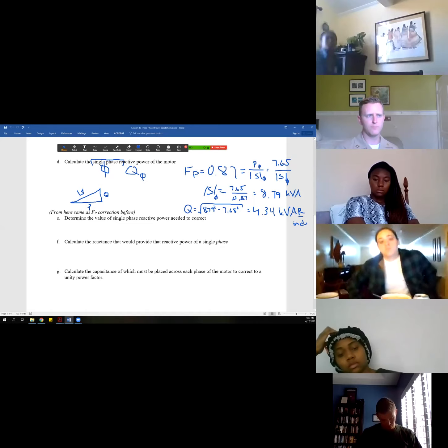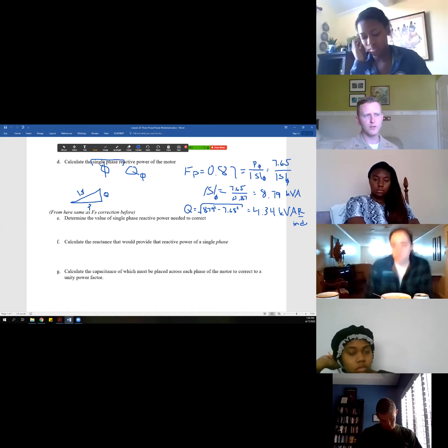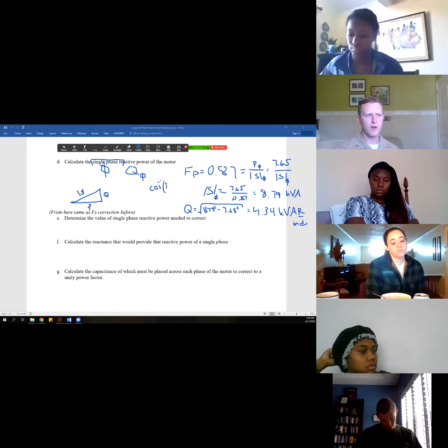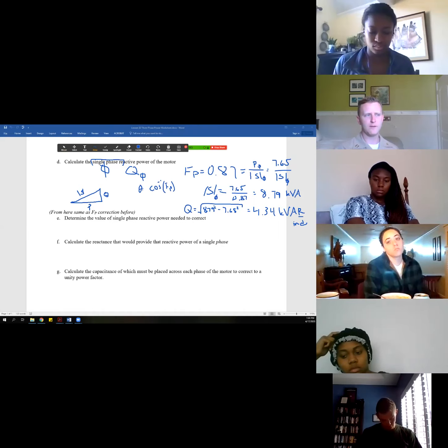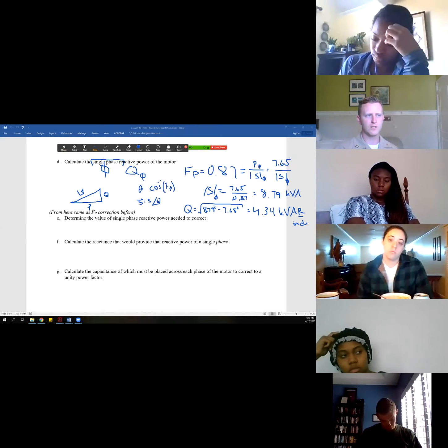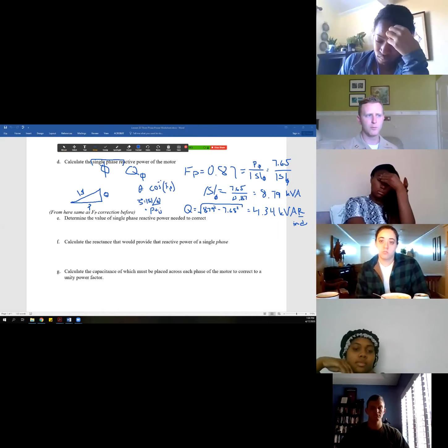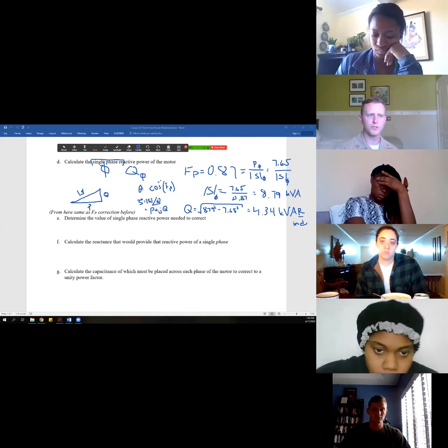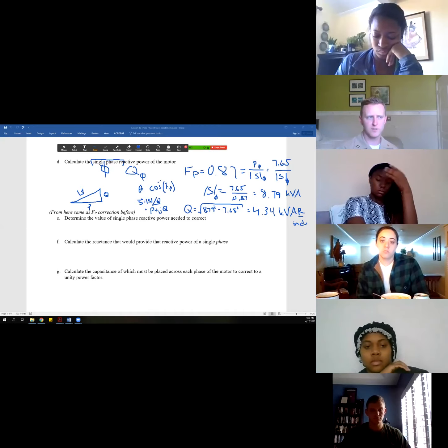But there's other ways to think about it. The theta would have to be positive as well for an inductive. The other way that you could do this is if you wanted to take the inverse cosine of the power factor, that would give me a theta, right? And if I had the theta, then if I did complex power, I could do S magnitude with theta, and go from polar to rectangular, and it would give me the P plus jQ. That's another good way to do it, because then whenever the P comes out, I should see that it equals 7.65. And it's kind of like a sanity check. If my P comes out to 7.65, I must have done the math right.